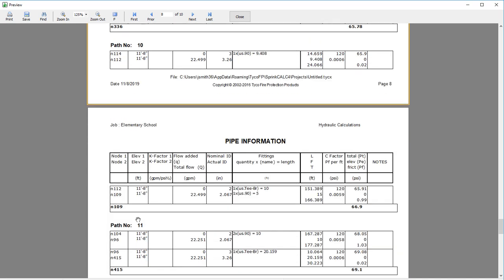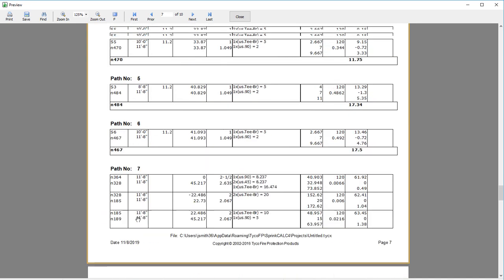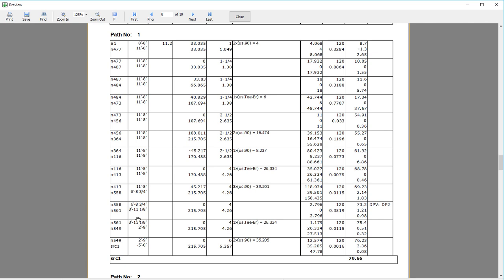As long as the pressures are guaranteed to meet in balance at every junction point, which they are because the computer is doing the work, then your calculation is very easy to read in path number 1. You see here that there's the valve. This is where the valve is losing 0.98 pounds, and we'll see the valve curve later. So this water is carried down the 1.25" branch line.